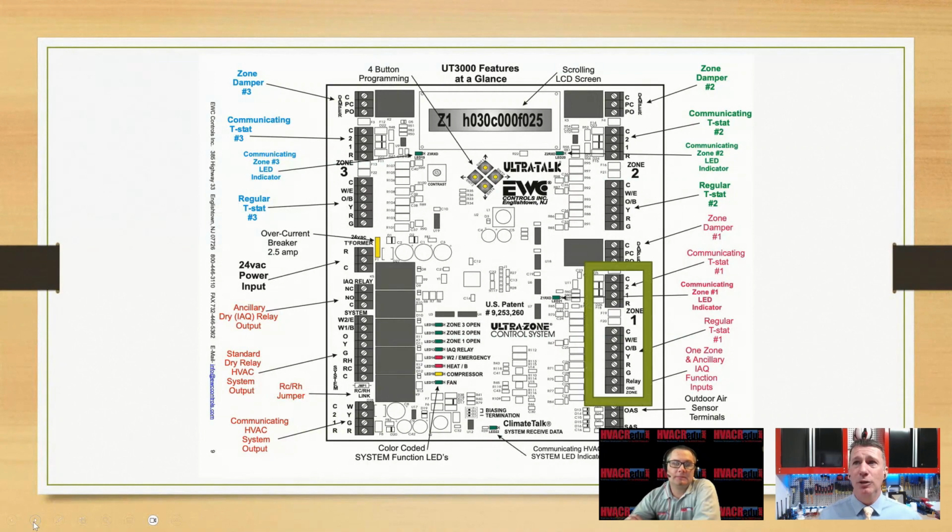If you look on that side, this is a zone control board that allows you to use either option on a communicating system. So it's got to be a communicating indoor unit and communicating outdoor unit. You can use either a communicating thermostat or a legacy thermostat. But what about the language? Yeah, so this is only for the Daikin network, the Daikin zones. There you go.